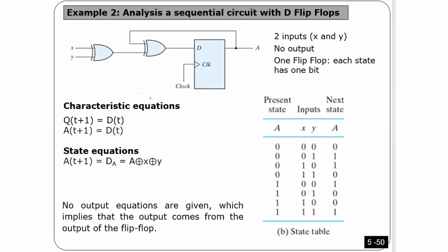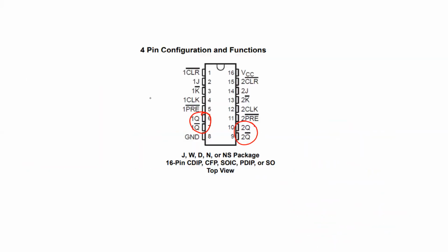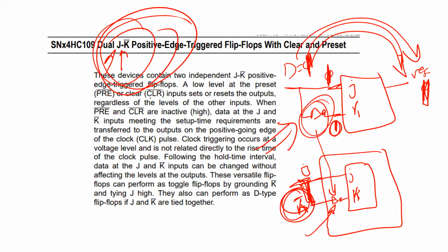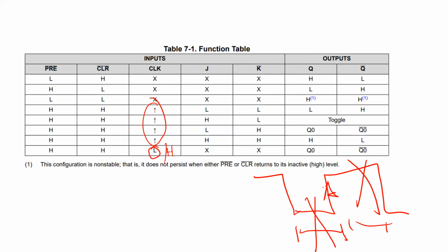So the first part in this lab, I want you to use this chip just to get used to the JK flip-flop and just explore the truth table. You see, I'm saying toggle. You will see if it is going to toggle or not. I'm saying it has to set or no change. That's what I want you to explore.